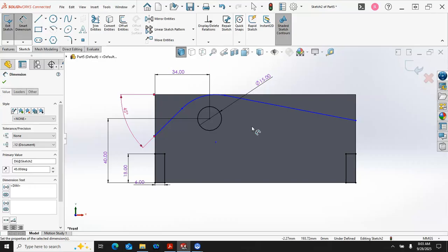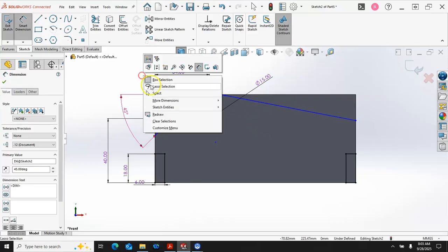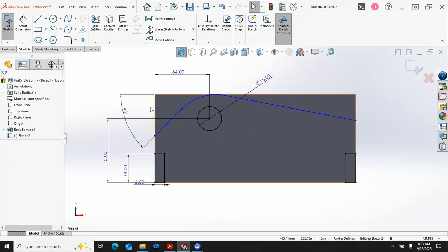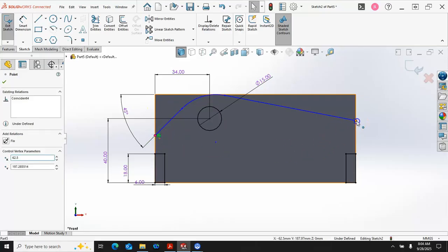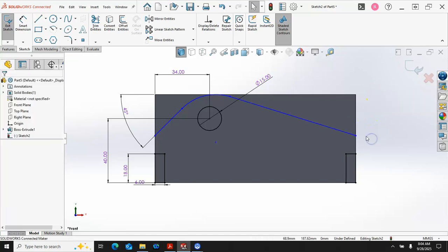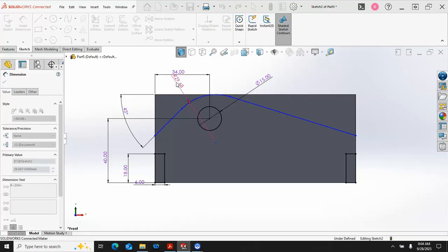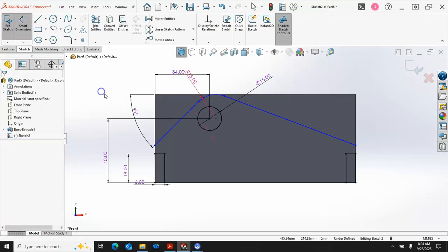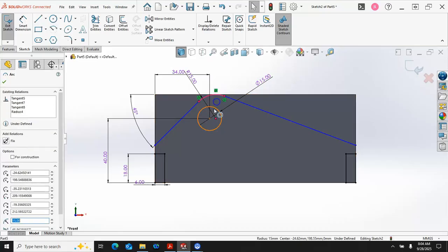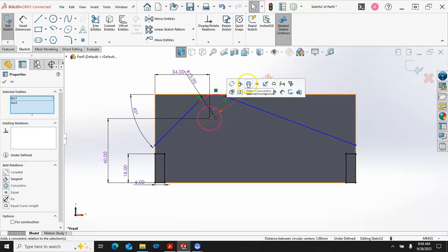Let's see the other angle. Well, hopefully that terminates. Let's see, there's an extension line. No extension lines to help with this one. Then we're going to make the assumption that these 2 endpoints are horizontal. All right, so radius of 15 for this guy. All right, so that gets our arc. Looks like, let's see, does our math add up? We were 55 overall and 45, so that would allow this to be concentric.